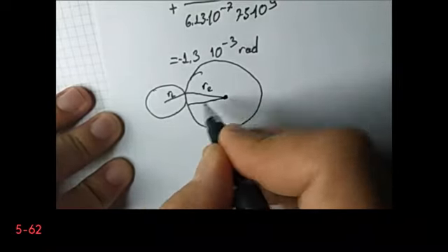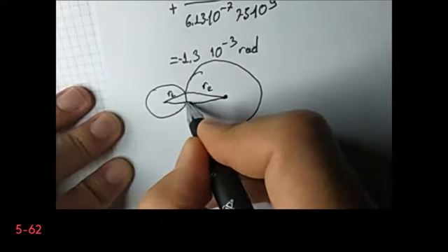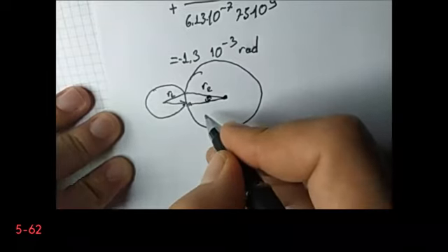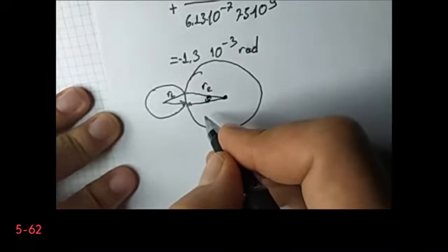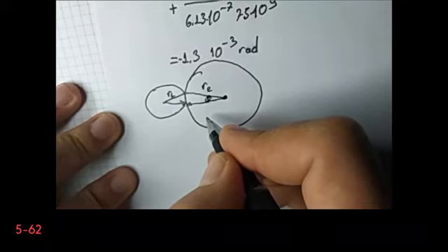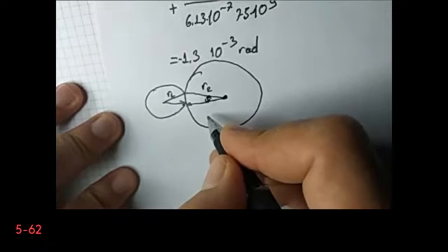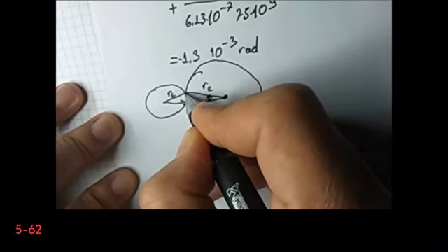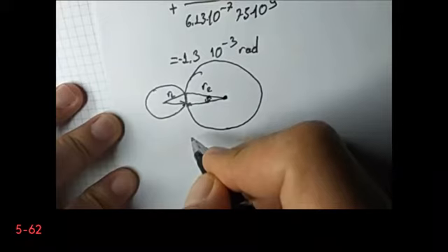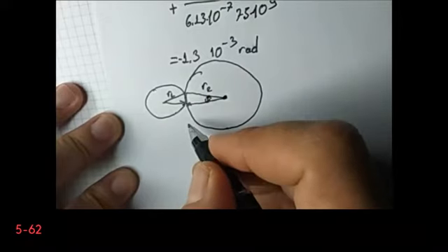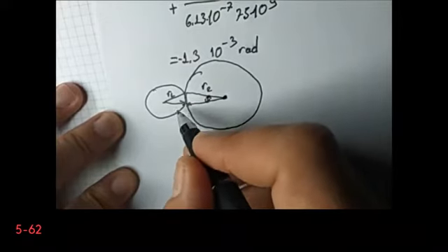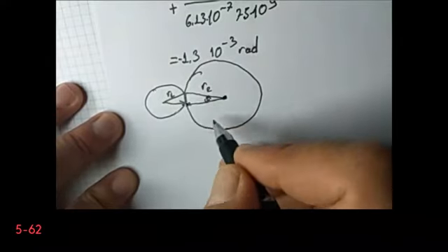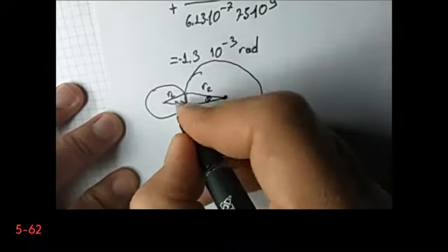Now, since the deformations are small, in fact, these two gears will make the same amount of rotation, not the angle, be careful, same amount of rotation. So therefore, the point on gear 1 will make the same amount of displacement with the point on gear 2. So at the point of contact, they will make the same amount of displacement.